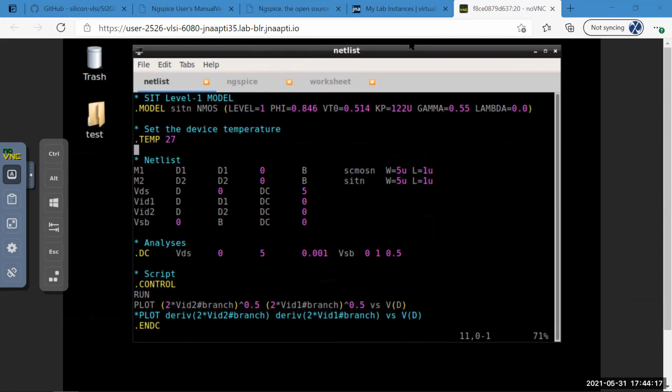So it's almost linear there. Whereas in the linear region the dependency is very high. On the linear side it is VDS dependent, so both your VGS and your VDS matter. If you take the square root of that, you're not going to get a constant term, right?